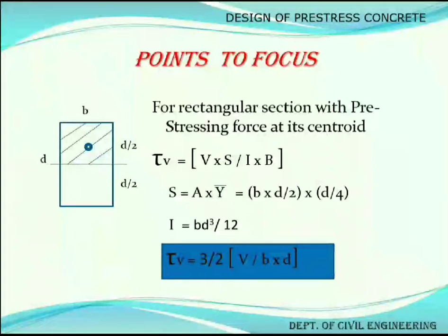So, points to focus on. I have kept them purposely so that you do not forget them. This is the same as explained in the previous video, where for a rectangular section the shear stress can be calculated directly using the formula 3 by 2 into V divided by B into D.